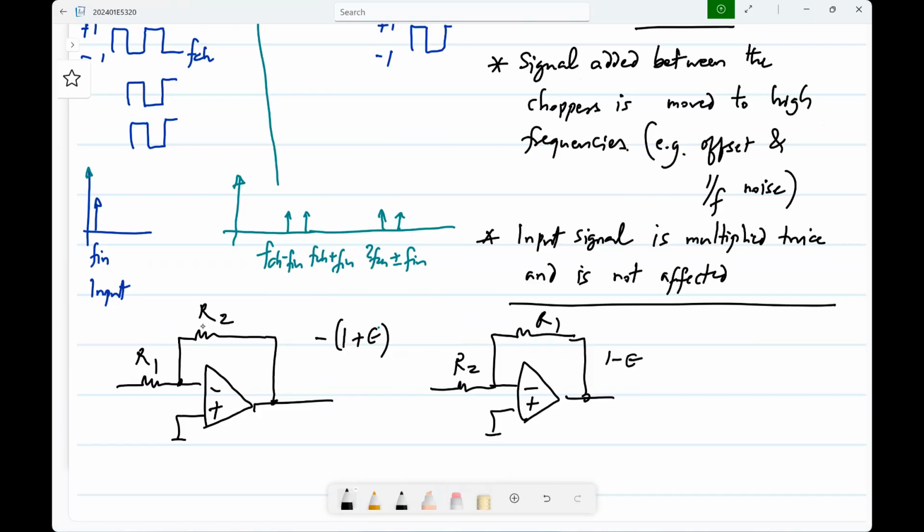Okay. So again, if the frequency at which you have this alternation is much higher than the signal frequency, on average, it looks like it's getting multiplied by 1. Okay. So these are dynamic techniques that are used. Again, there are lots of details, but at least it's possible. With this, essentially, the mismatch more or less goes away, right? Of course, this is applicable in a restricted context. Again, you are now dealing with time varying signals, etc., etc. Okay.